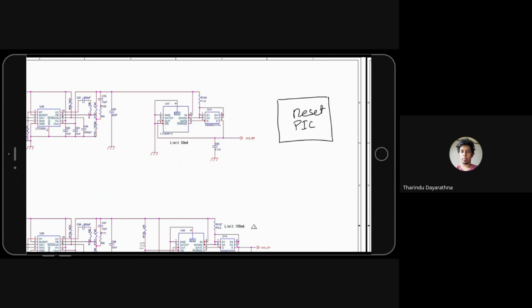Okay, if you get the reset peak, in nominal condition, peaks consume about 20 milliampere. Okay, so which means 50 milliampere is no problem. There will be no OCP triggering.